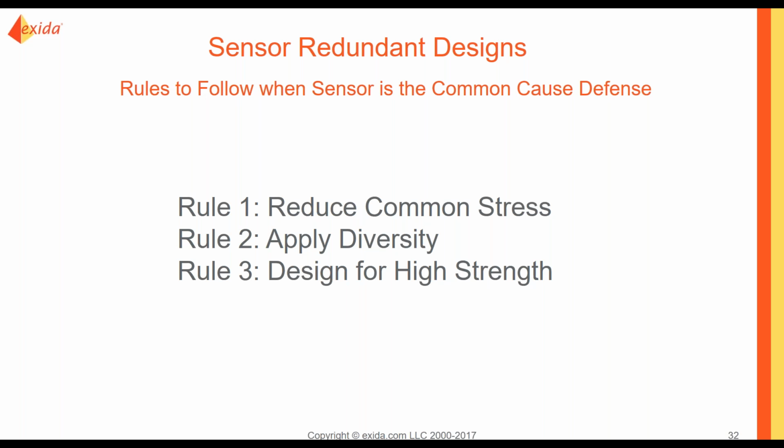Consider a design where three smart safety certified pressure transmitters from three different manufacturers are chosen to be a 2 out of 3 architecture. All three transmitters use a diaphragm assembly. The calibration and maintenance procedures are different for each transmitter. The configuration tables are different.